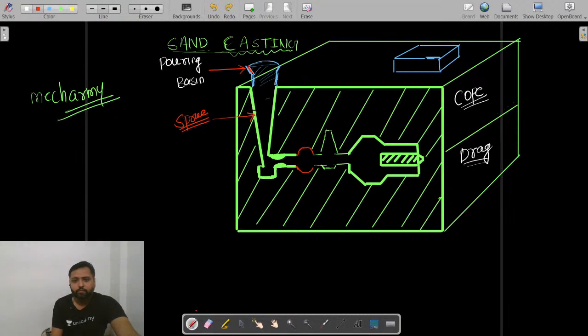You see, here we place a filter inside the sprue. This filter which I am showing you, it looks like, have you seen the coin of the carom board game? Like this? And there will be, suppose, these small holes in it.